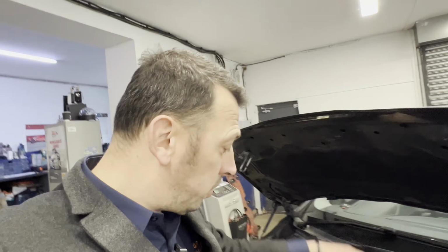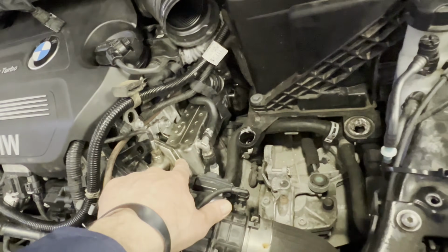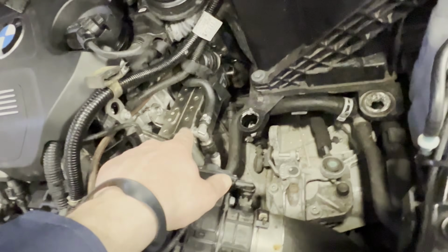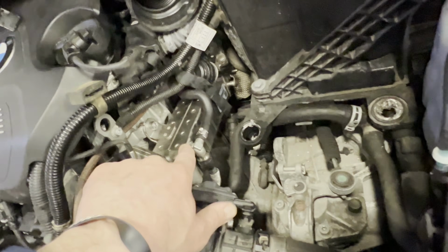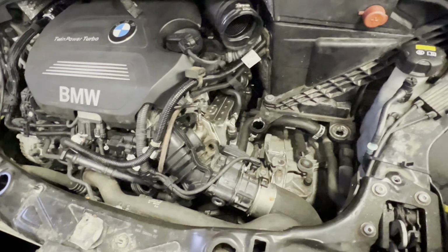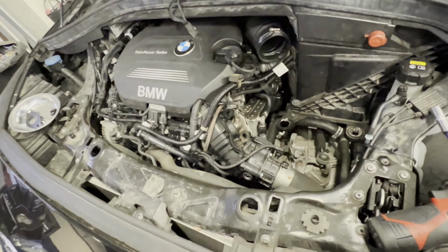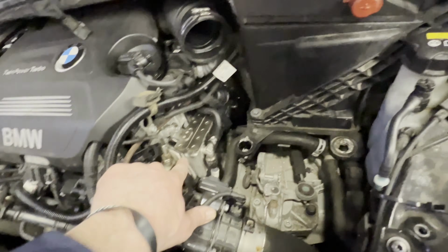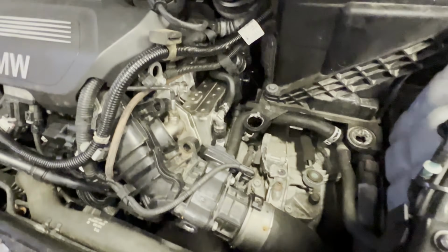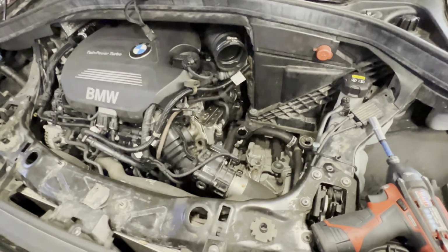But on the road test, you've seen it kept bringing a fault related to the mass airflow values. Obviously, with that blank on the EGR, the values were incorrect in correlation with what the ECU was expecting to see. So this should solve the problem. We have also checked, and it looks like this car is going to have a recall with the main dealer for the EGR cooler. But we are concerned with our problem, to see whether this fault is going to clear. We need to order a gasket for this one because the gasket was missing, then reinstall and take it on a road test.